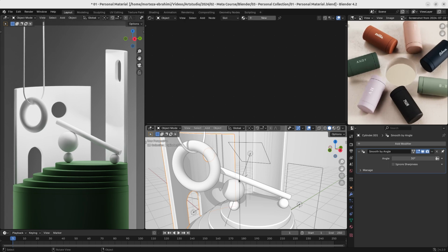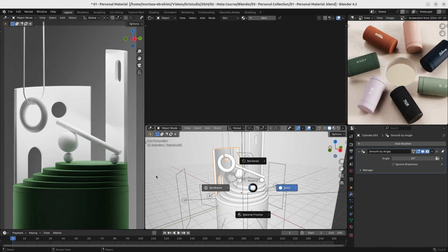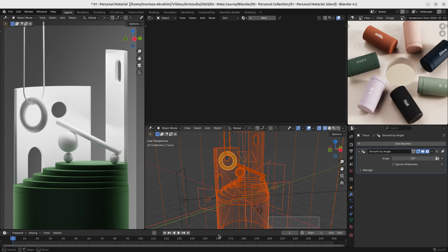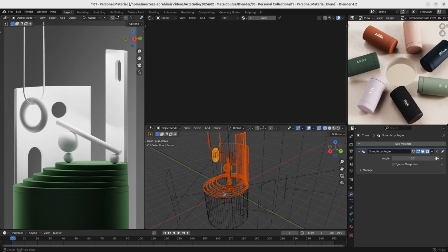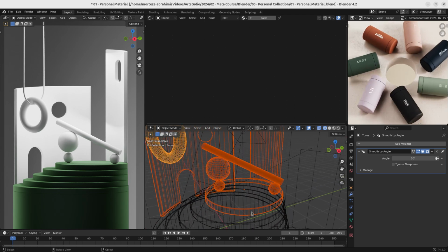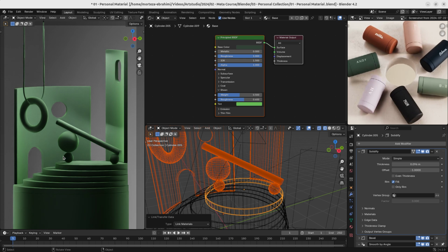Okay, so let's select this one and we can actually copy the same color. Let's select all these other objects. Let's select everything except these lines. So now make sure to select only those, and then one of these which has the material, so Control L and link material. So now we actually assigned the same color to all of those, which is interesting.